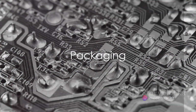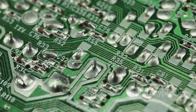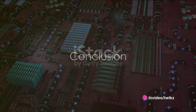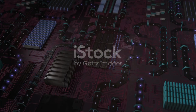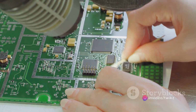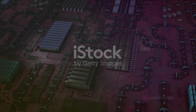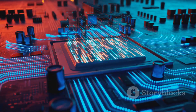Finally, after rigorous testing and verification, the chip is packaged and ready for distribution. The packaging protects the chip and provides the necessary connections to the outside world. To summarize, the VLSI design flow is a systematic process that transforms a system specification into a tangible, functional device. It involves several stages, including system specification, architectural design, logic design, circuit design, physical design, fabrication, testing and verification, and packaging. Each stage has its own significance and contributes to the overall functionality and performance of the device.